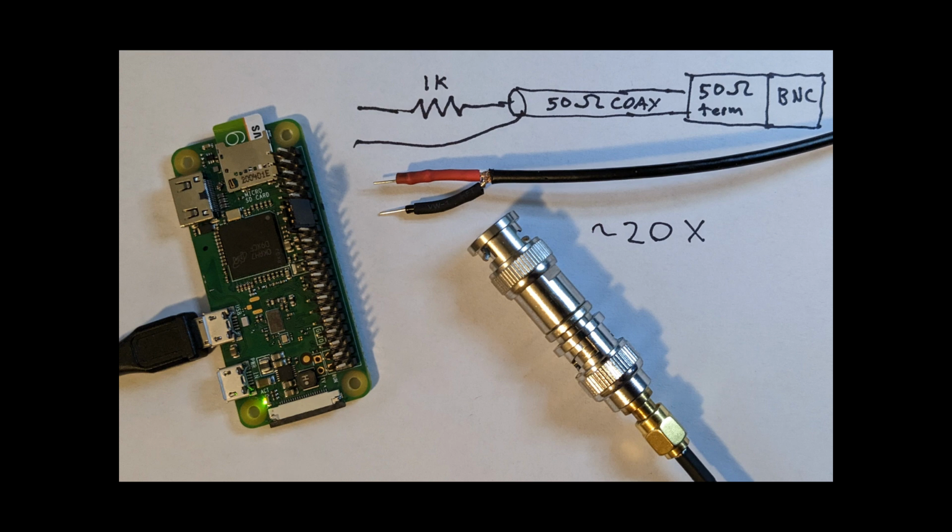By the way, this kind of cable is discussed in the third edition of The Art of Electronics by Horowitz and Hill, and they claim that this technique is how they get such clean scope output captures for their book. But it does have this issue that it loads the circuit more because there's only that 1K resistor there. And so you can't always use it. And people that know more about this than I do say in general that these cables shouldn't just be thrown together, that you have to know what you're doing to use them reliably. But it does seem, especially with a 100 megahertz scope, that you can get pretty good results just by making a cable this way, essentially thrown together with parts out of your drawer.